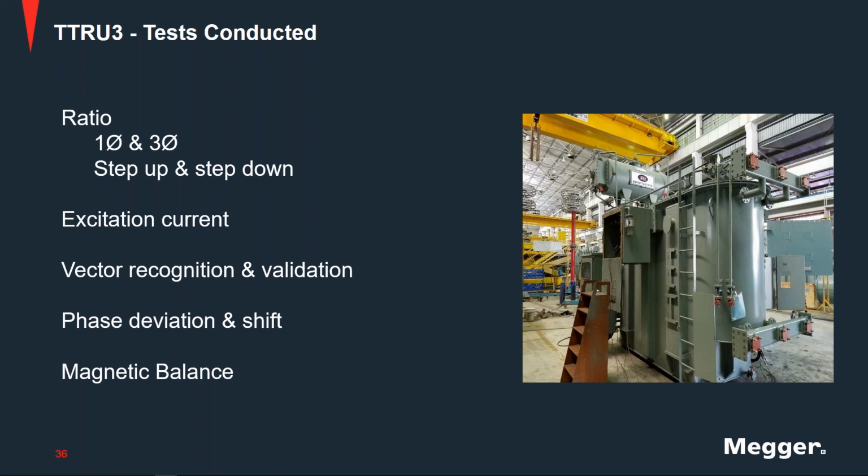So if you excite phase A, it will look at the ratio of induced voltage on phase B and phase C. It's typically used in India during transformer construction to look for any problems when they're winding the core, or when they're putting the winding on the core. But it can also be used to validate the state of magnetization within the transformer, which is where we would expect most people to find value in that software feature.